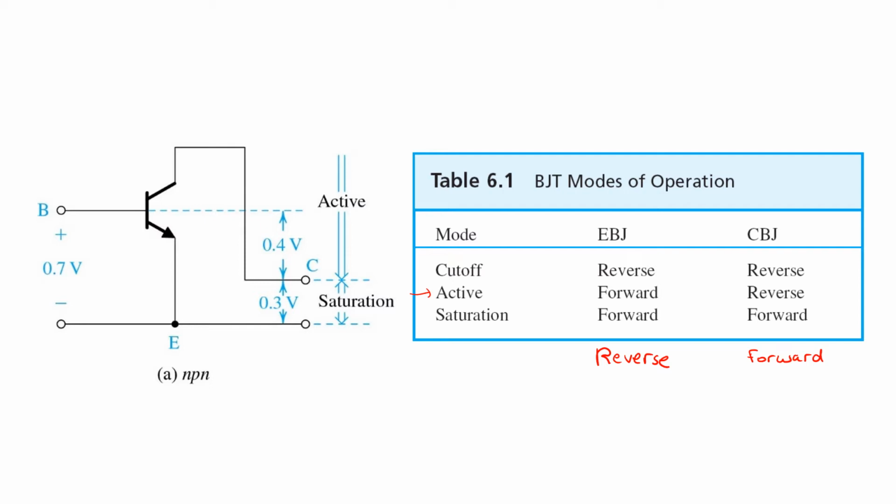The same is not true when it comes to the base collector junction. In fact, the collector junction is also often relatively weakly doped. And this is done in order to allow it to have a relatively high breakdown voltage in some cases. Nevertheless, the point is the emitter is particularly heavily doped, and so the device is asymmetric.